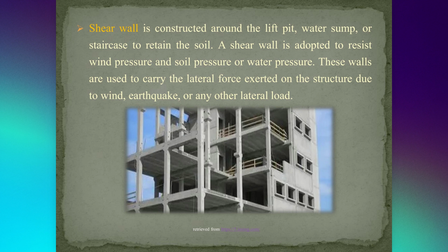Shear wall is constructed around the lift pit, water sump, or staircase to retain the soil. A shear wall is adopted to resist wind pressure, soil pressure, or water pressure. These walls are used to carry the lateral force exerted on the structure due to wind, earthquake, or any other lateral load.